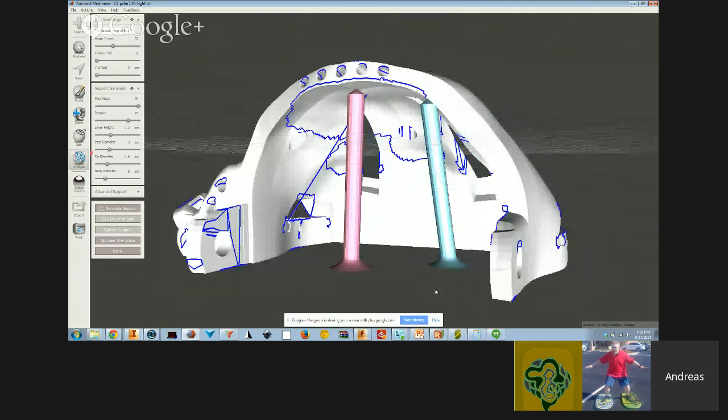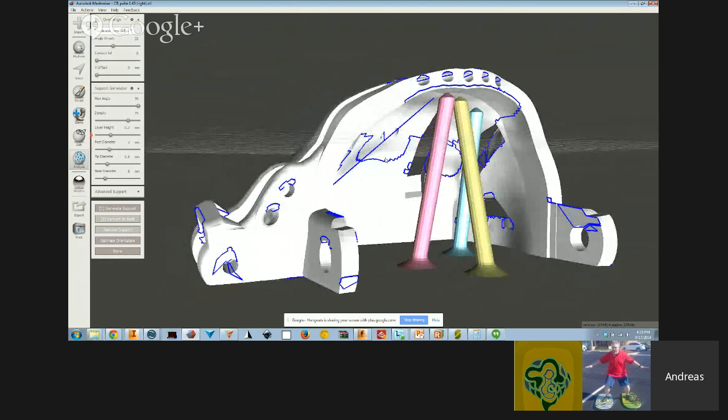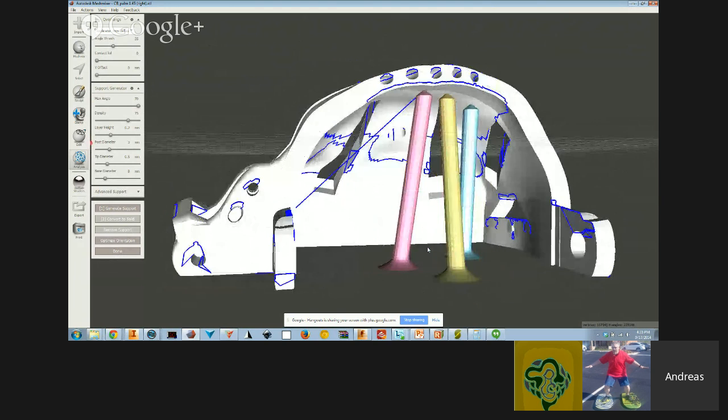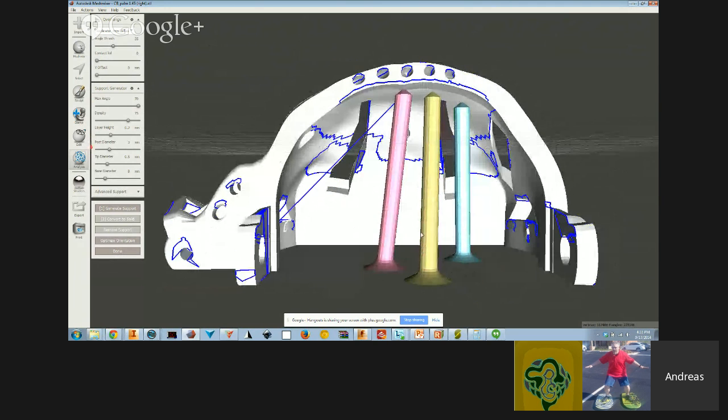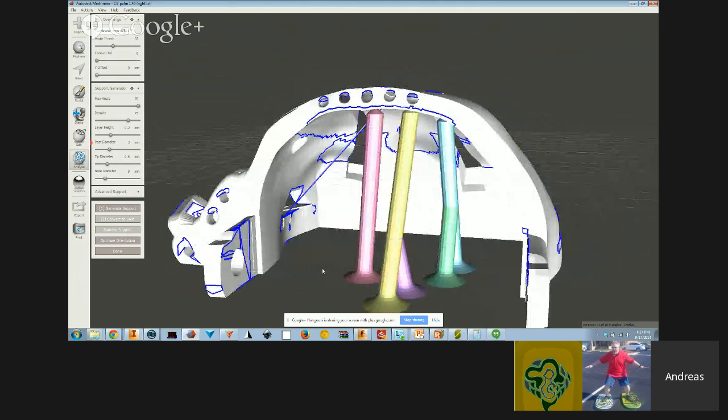Port, you can just keep clicking in an area and it'll search for supports. You saw some of that branching that I had. If you want, you can click on those branches and it'll add struts here and there. So it's good to know, in general, left clicking will add. You can click on the support and it'll add this little brace here. Clicking on the model, clicking on the support will add more of those things.